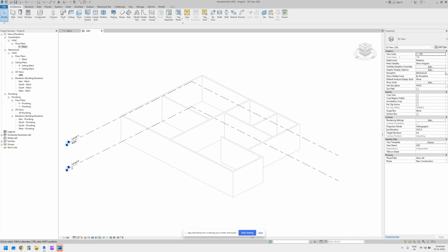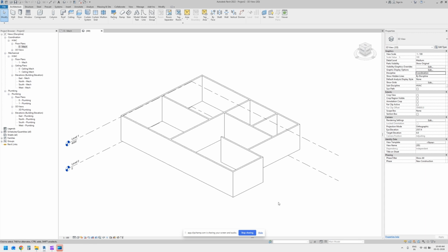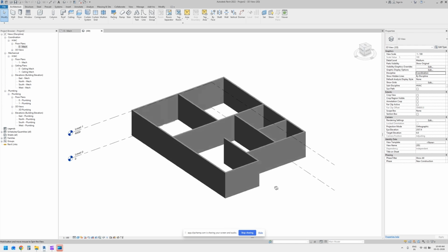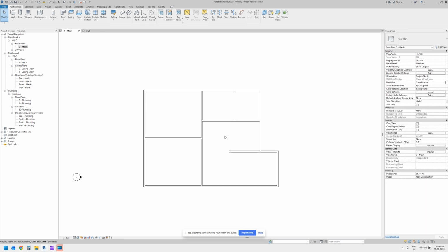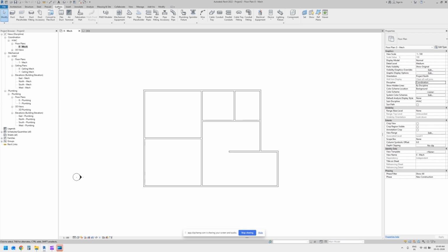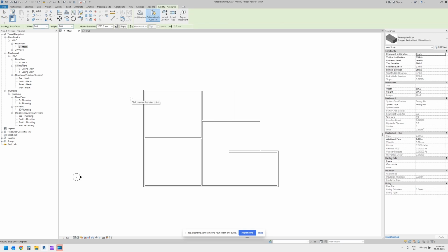For the purpose of this exercise, we are not drawing any doors and other elements. We are just doing the walls. And now within the same model, we are drawing the services. So we'll go to the system panel and pick duct. From its elevation, it will be around 2750 up.